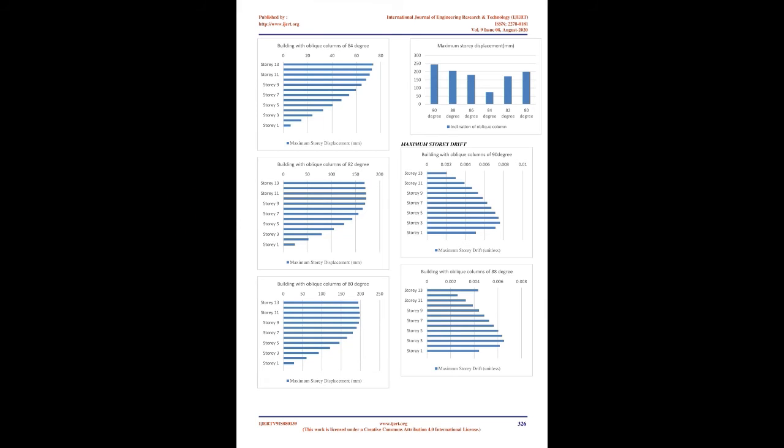Further, the seismic analysis of structures cannot be administered simply by using the peak value of the ground acceleration, because the response of the structure relies upon the frequency content of ground motion and its own dynamic properties. To beat the above difficulties, the earthquake response spectrum is the most well-liked tool in the seismic analysis of structures.